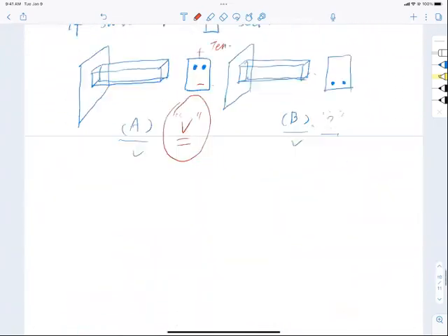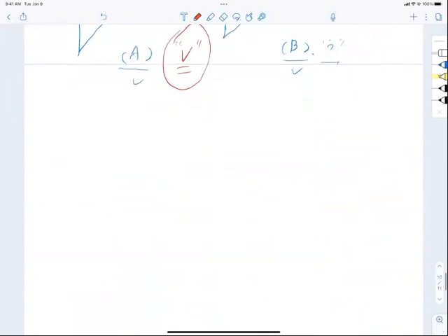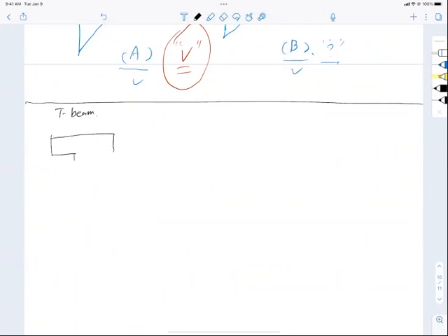So now get back to the T-beam design. Going back to the T-beam, I'm just gonna put a division line here. We are looking at a section like this, and we already selected 8 number 9 bars: 1, 2, 3, 4, 5, 6, 7, 8. No matter how I do that, there's going to be 20 inch of depth right here, and that is my d_s. I fix that, and no matter what I do, I have to maintain that.